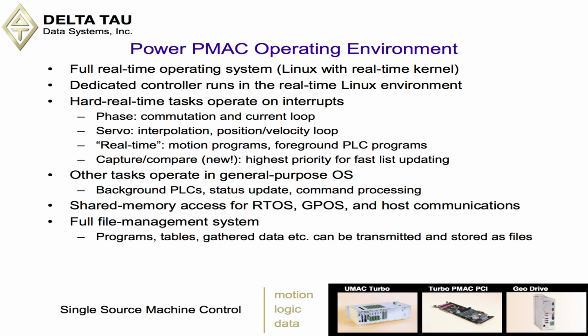Okay, the operating environment. We have a full real-time operating system based on Linux, where we've added a hard real-time kernel. Plain vanilla Linux is multitasking like Windows is, but also like Windows, it is not hard real-time. And while for many tasks it's fine to have it just cyclic, that is not suitable for real-time control, for servo kind of thing. There must be a very well-defined latency for this type of motion control. Otherwise, you get servo hiccups from missing a beat, and that can destroy things.